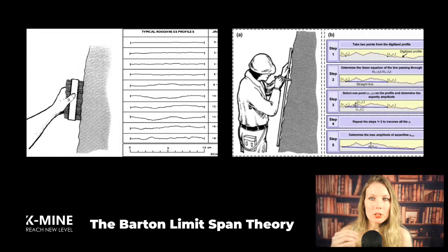These parameters define the stability of rock bridges within the stope, enabling engineers to design the stopes that minimize the risk of collapse. A key insight from this method is the weaker rock masses require narrow stopes and additional support structures to prevent failure. The Barton approach is often used in conjunction with the Matthews stability graphs to refine stope design criteria.